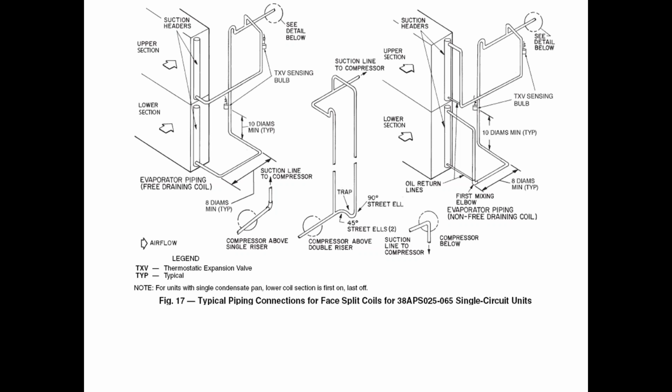We'll get the equipment submittals, and I'll have that part, and then I need your pipe drawings, and then I'll be able to give you some drawings back of how to manifold all the suction stub outs together, how we manifold the liquid, how we do all that, and your TXV sizing, because when you get into a 12 or 8 TXV manifolding job, it's an hour's worth of work. Easy to get it right and get everything calculated out. So, just like I say, get that over to us, and we will help you through that.